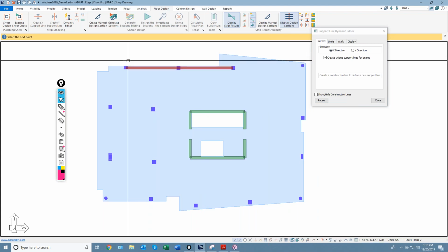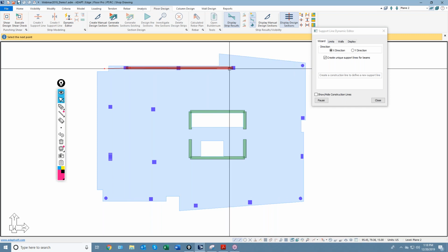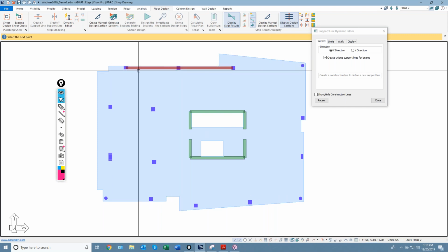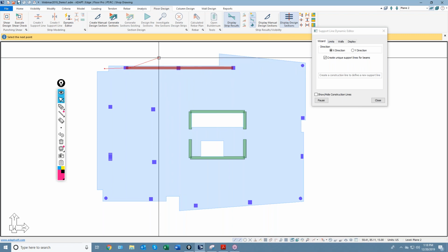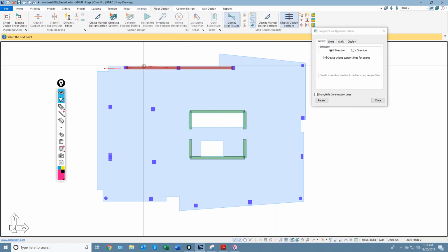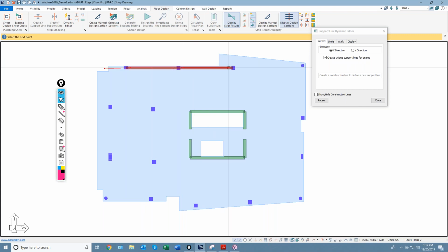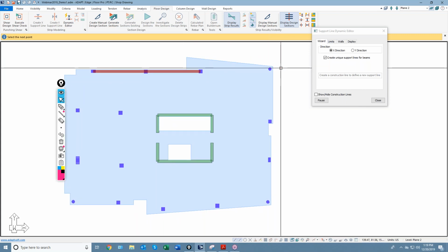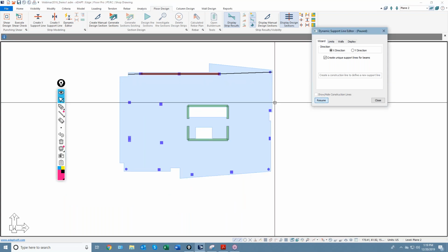Now, if I snap at point 1 and all the way over at point 2, it's not going to work because these beams are actually segmented. There's actually 1 and 2, so I need to snap near point 2 of beam 1, near point 1 of beam 2, and then point 2 of beam 2. And then out. The program will break this up.